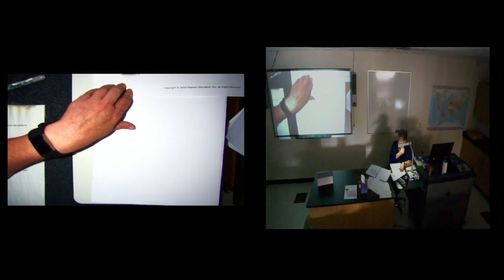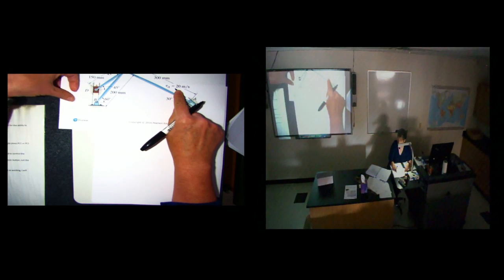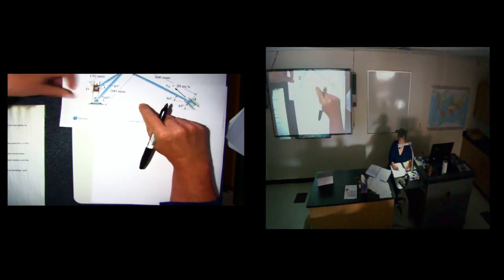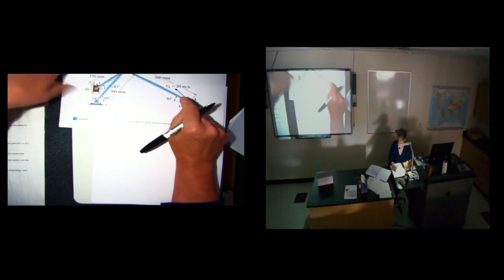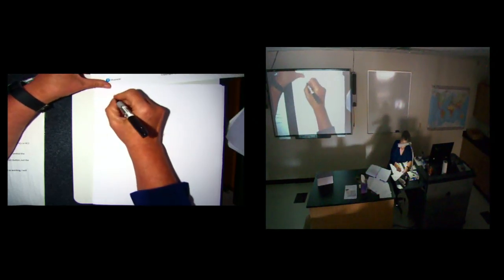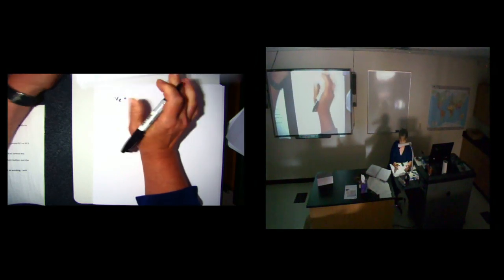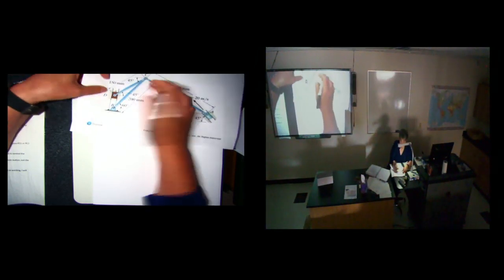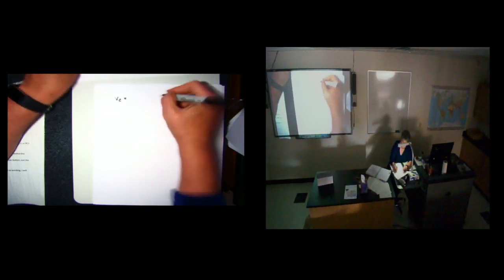I'm going to go ahead and write out VA. We've got this piece here, and this is the angle I have to use because this is directly in line with this piston right here. So my VA is minus 20 cosine of 45 degrees in the I direction plus 20 sine 45, and then I've got to have RAC.